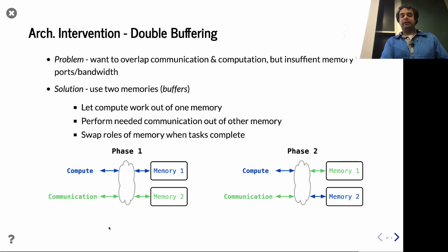So basically, in other words, if I have some sort of application where I can somehow divide my memory for computation into two different units, I have element 1, element 2. I can be computing on element 1 while I'm transferring element 2. And then when I'm done computing element 1, I can start computing element 2 and start transferring the other one, right? And so the buffer is just a way of having the hardware all working in parallel. One piece of hardware is doing a transfer while another is doing the compute, and you can swap which one's which.